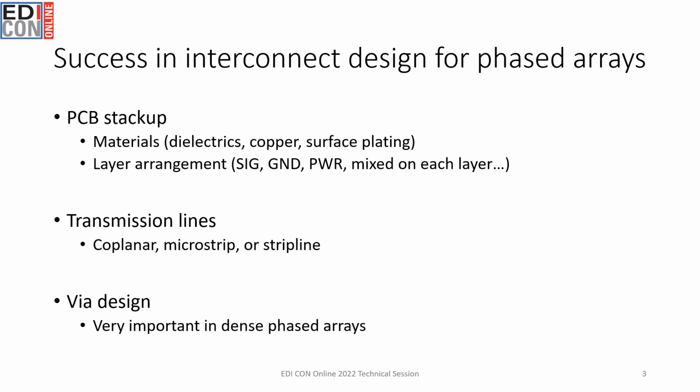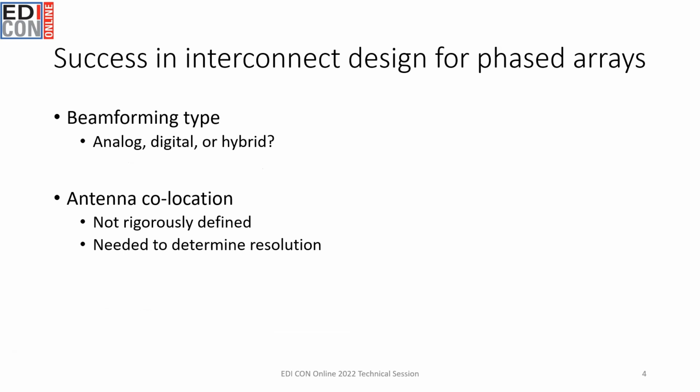Now, one of the big challenges in phased array systems is the number of antenna elements. It just keeps going up. And this is creating a challenge in terms of getting signals into antenna elements, and it is requiring via designs that can support wideband signals, or that can operate in a narrow bandwidth, but at very high frequencies. And so we'll look at some design options for that as well.